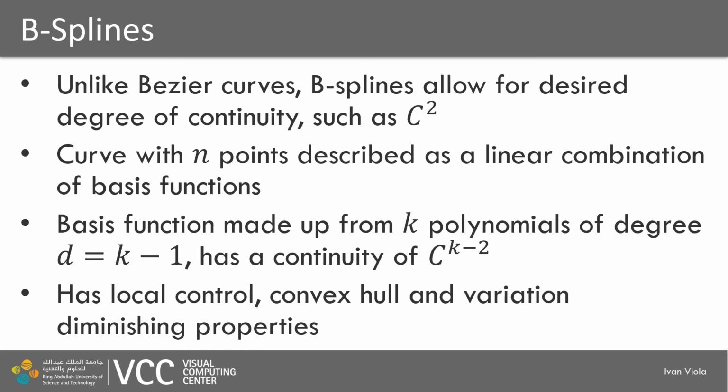However, with the B-splines, despite the given number of control points, we can vary what should be the polynomial degree which blends our basis functions. So with the same control points, we can have just a linear concatenation of a polyline or much higher degree polynomials, which will be formed by the blending of the functions.